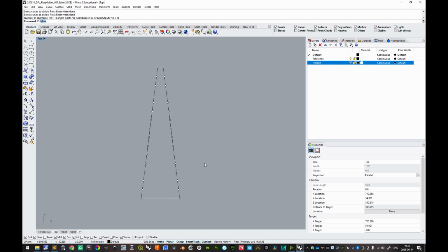Now we can create a polyline, and a polyline can start at this point here, and we want to make sure that we disable the snapping for near and that we enable the snapping for points. And in this case we could actually right mouse button click on the point snapping here, so that it's only points that are snapped to. And then we can create a pattern like this, perhaps every other point, like that. And I think that this is going to be too tight, so we can leave it here. So space or enter to confirm. Very good. And now we can re-enable the snapping, so we right mouse button click here, like this.